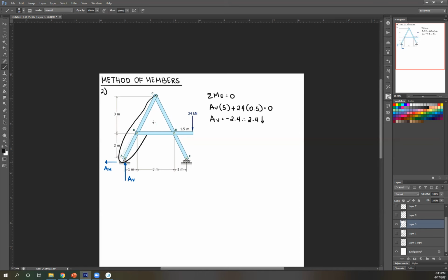So if I analyze ABC, this member, I'm going to have a lot of unknowns, right? So we have an unknown here and here. So that's 4 unknowns. So I'm going to have to figure out how to lessen one of those. So usually to do that, you look at the other members connecting to those hinges. So you can either look here or look here. Now, if I look here, it's the same thing as the other side. I'm just going to take reactions here. Then once again, there's going to be unknowns. So most likely, this is what I'm going to isolate next. So let's try that. Isolate member BD.